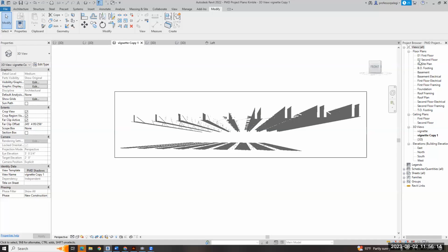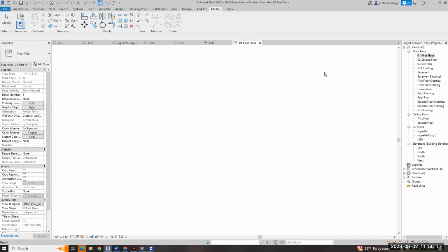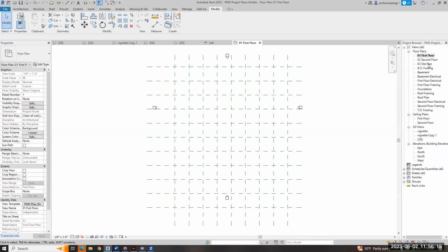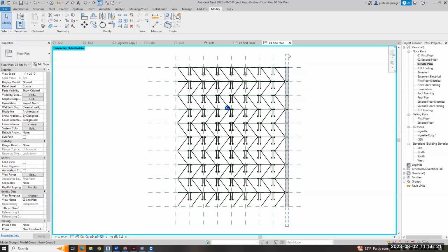So this is one that I had. What I did really quickly is, if I want to use the divided surface, I have to make a massing in place, and then divide the surface and then load that thing in. But I could also just make a grid with my lines 10 foot by 10 foot, and I have intersection points.